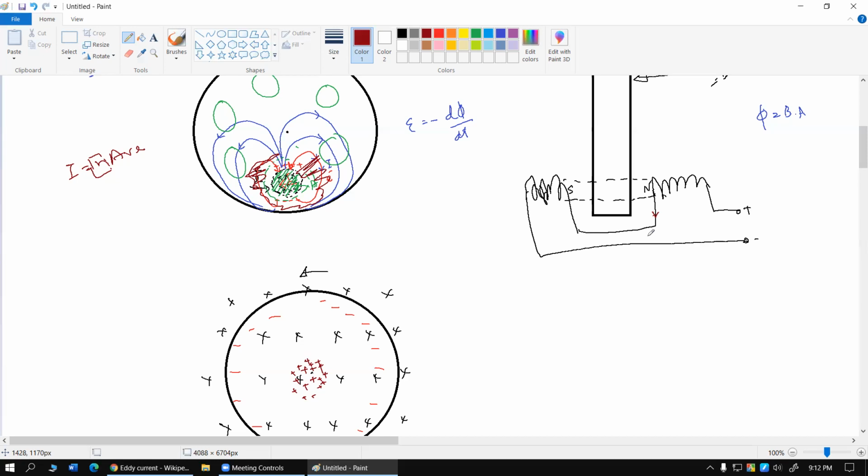So for them, electromagnetic braking might not be a very good idea, but some supercars which are designed for very high speeds, or maybe Formula One vehicles which might want really fast braking in this manner, might have this kind of technology involved, provided it suits their weight ratio, because every gram of weight in a Formula One car is very important. The more you can give up, the faster your car will go. So depending on all the factors, if your vehicle is designed to run at a pretty high speed for a prolonged period of time, electromagnetic braking can prove to be very useful.